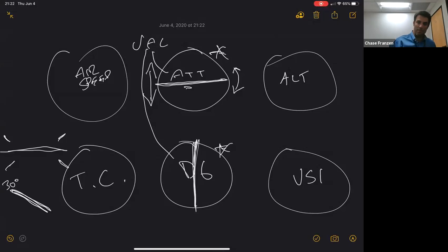At the bottom of the turn coordinator is the slip skid indicator with just a ball inside of the vial of kerosene, most are, that just shows you the coordination of your turn, or whether there's centrifugal force that's drawing to one side of the turn or other, whether you're slipping or skidding, whether the rate of turn matches the bank of turn, whether your tail is moving at the same speed as the wings. So that's what the turn coordinator does. The slip skid indicator, the ball, there's nothing powering it. It's literally just a weighted ball sitting inside of a vial of liquid kerosene that moves back and forth depending upon the centrifugal force, the forces exerted on that ball.